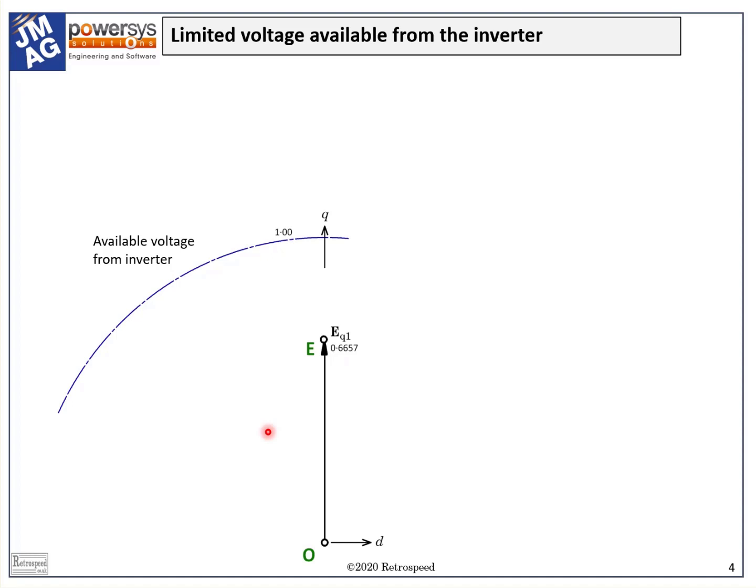The available voltage from the inverter is the RMS AC value of the fundamental time harmonic volts per phase expressed in normalized form or per unit. The actual voltage waveform delivered by the inverter to the motor terminals is far from sinusoidal. The relationship between the AC fundamental voltage and the actual voltage waveform depends on the pulse width modulation strategy, as explained in the Green Book, Chapter 7.